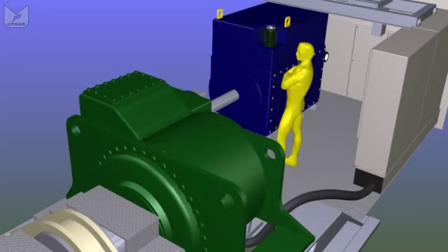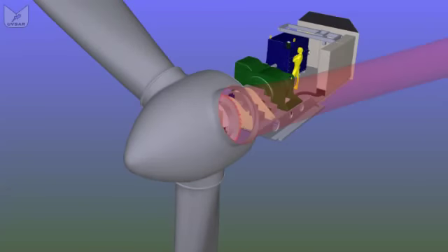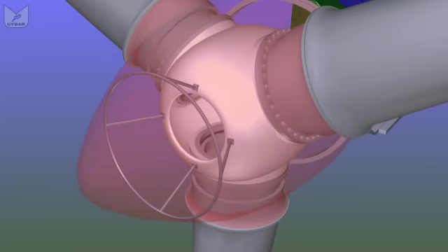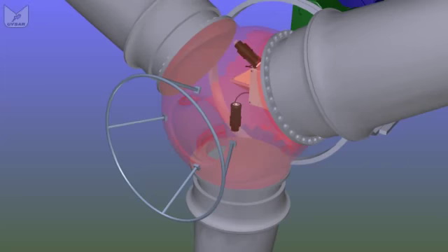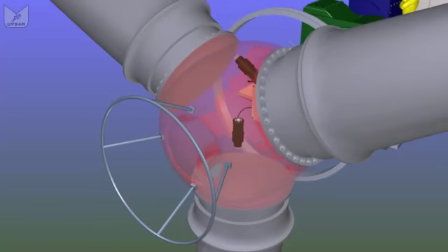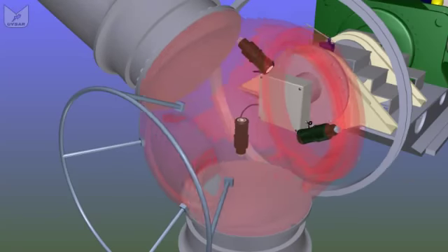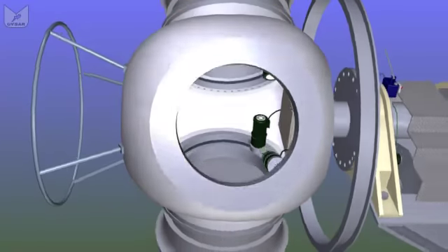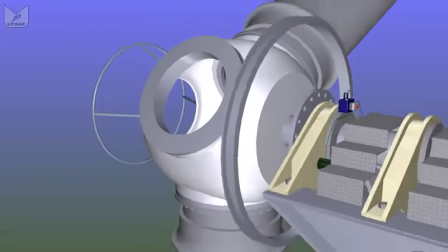The only thing left to talk about are the blades, obviously, which actually do the work. We still have 3 of them. They still pitch, in other words, they twist on themselves to line up with the wind. And you access the hub through the gap between this fiberglass cowl and the cast hub. It's a bit of a wriggle, but you wriggle through, usually feet first, crawl through the hole in the middle of the hub, and inside the hub we'll find the control electronics, the pumps, the motors and the batteries to control the pitch of each blade, rotating it on its own bearing to set the optimum angle for the wind. If we turn the blades through 90 degrees so they're edge on to the wind, there's no net turning force. It's a process called feathering, and the turbine will stop.